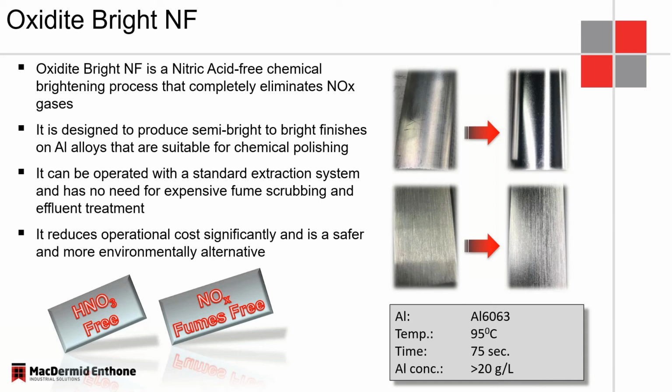And you see quite nicely from these pictures, we start with a very, very dull surface, and we end up with a nice specular, semi-bright, technical bright surface. One of the benefits here is, again, no nitric acid, no nitrous oxides. We don't need fume scrubbing or any dedicated effluent treatment for the wastewater.